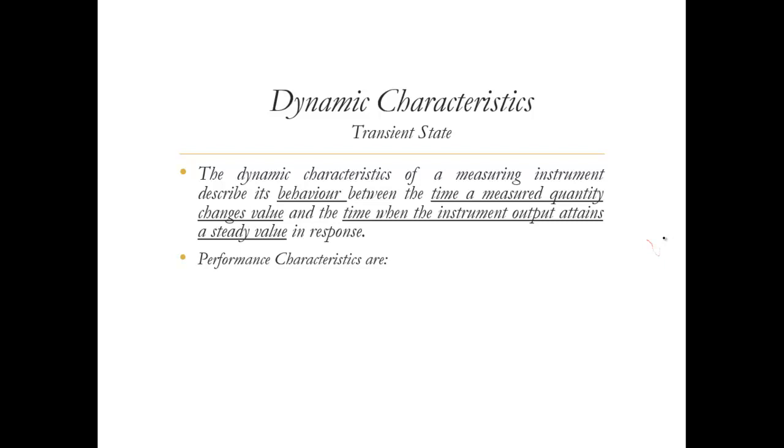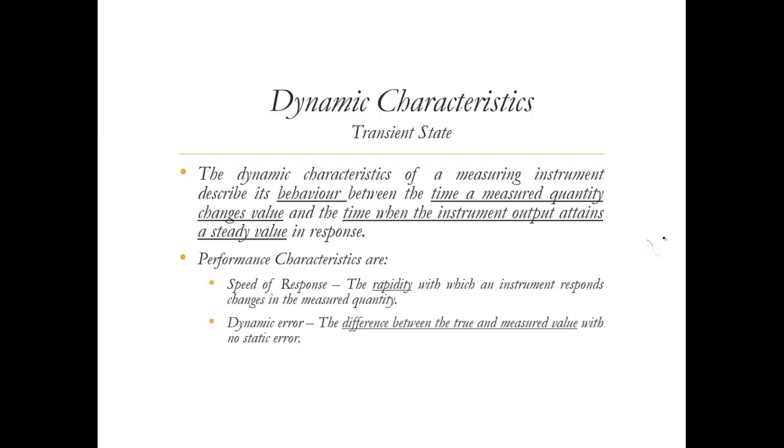Now in this case, the performance characteristics become something called speed of response. How rapidly the instrument responds to the change in the measured quantity. For example, now the temperature changes. How much time does it take for the instrument to come up with the final value of the new temperature? So that's very important, that we call speed of response.